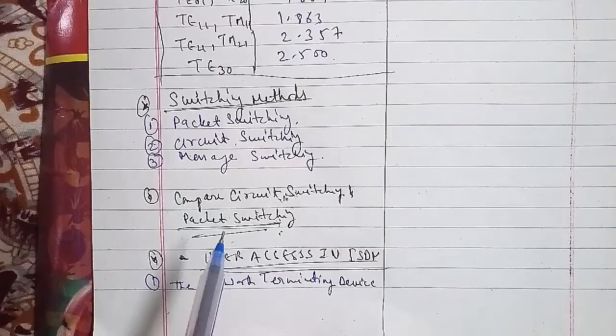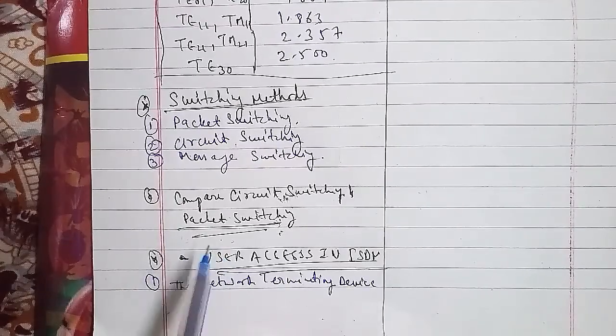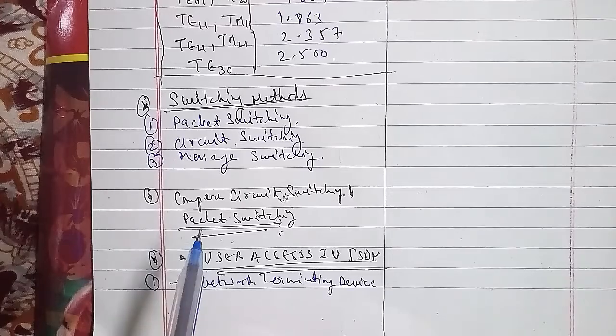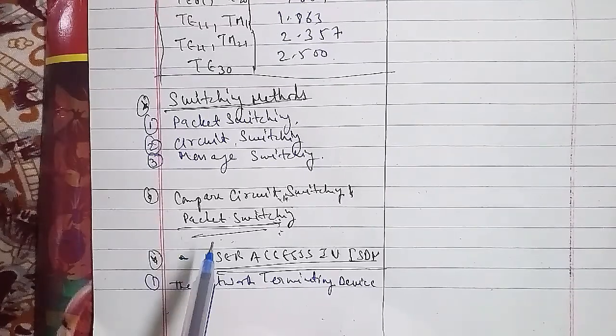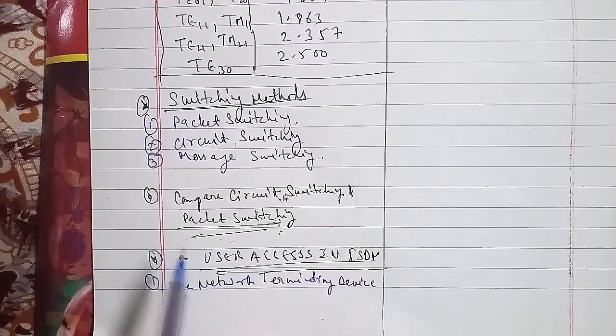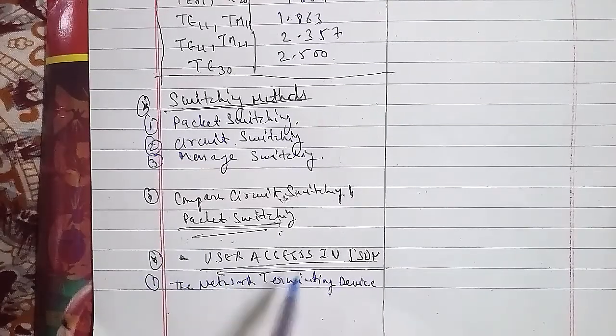The S interface is an 8-wire interface, of which 4 wires are mandatory, and it connects the terminal equipment to the customer switching devices, such as PBXs, for distances up to about 2000 feet.